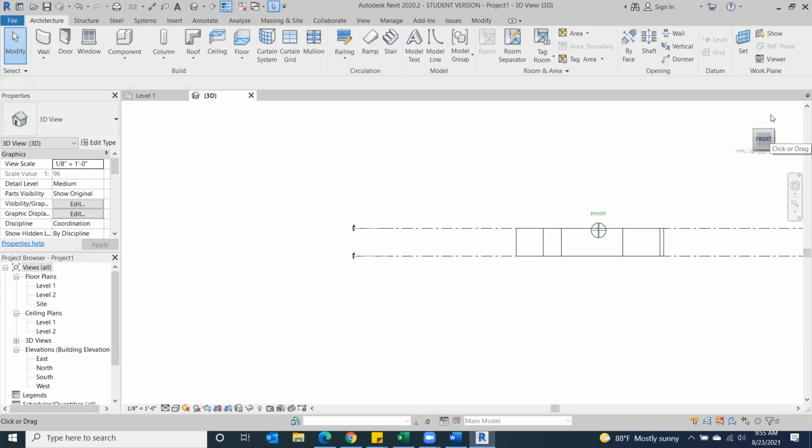So when you start drawing your initial floor plan, if your walls default to 20 feet, leave them at 20 feet. There are different ways that we can adjust the height. Notice how it said it was connected or unconnected. Well, there are ways that we can connect things and manipulate things how we want. So when you start drawing and you notice that you have 20 feet walls, leave them at 20 feet.